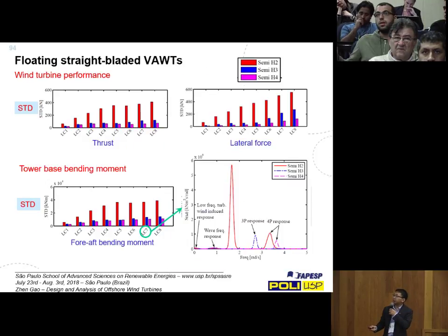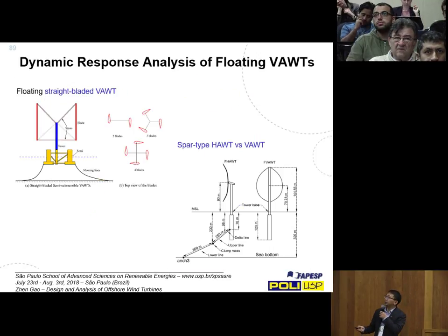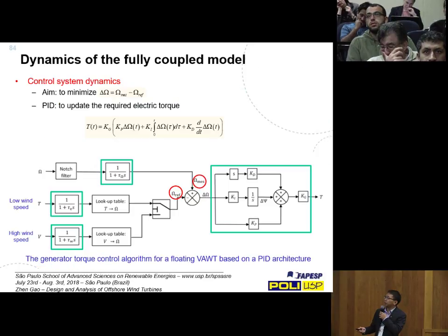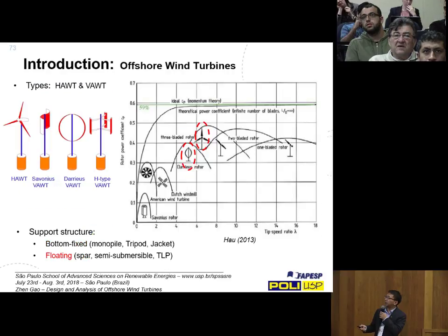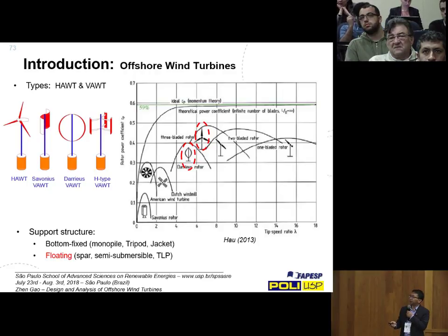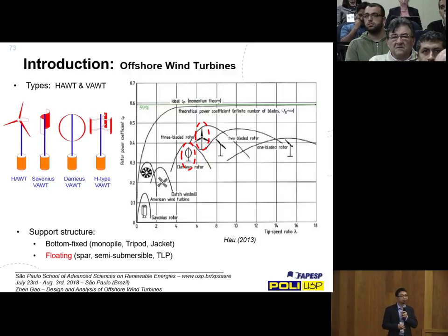As I mentioned, for that turbine you basically use lift as the driving force, while for the Savonius turbine you use drag, and then of course the efficiency is much less. For the drag-driven turbine, I did not explain it here, but it is shown here. The power coefficient is 0.1, while here we have 0.35 and 0.5. So for large-scale turbines, I don't think we will use this drag type of turbine.